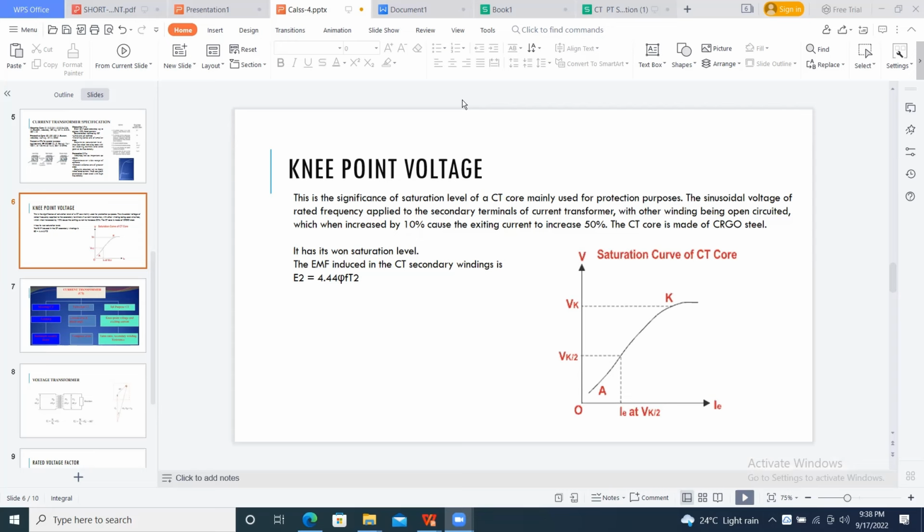Okay, I understand, but for protection, we do not need to worry. We can choose 100 VA even if we require only 5 VA? No, not for protection. There should not be much gap. The secondary side has to be taken care of, the relays to which you are connecting in the protection.